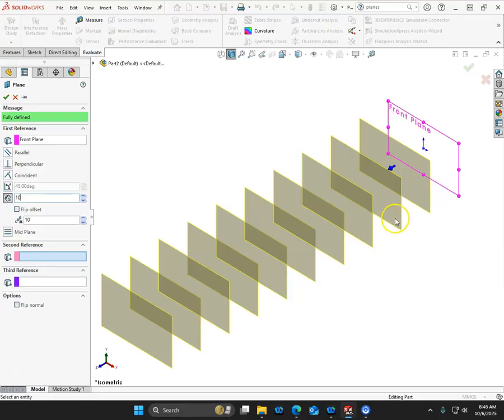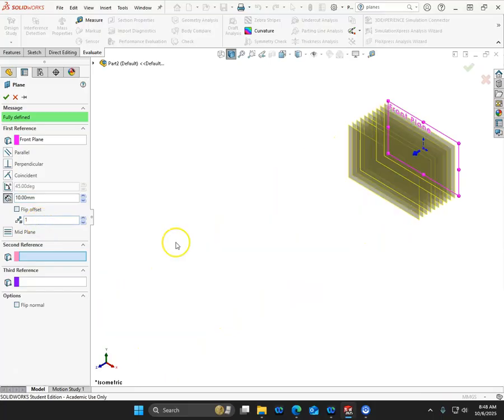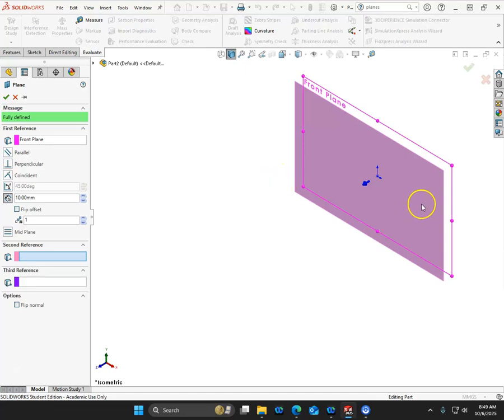So if, for whatever reason, I'm creating different gaps between the planes, then I can go back and modify the distance on those planes after the fact. All right, so we mentioned the different items. We have parallel. So parallel at a point, I would select a second reference. The surface at a point, I would select a second reference. The angle usually needs an edge or a line to act as the axis that it's revolving around, or the axis the angle is in relation to. So there's different combinations as we encounter our planes.